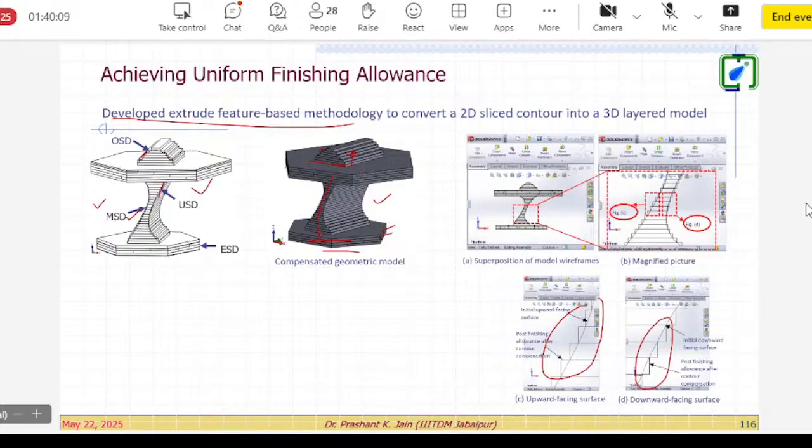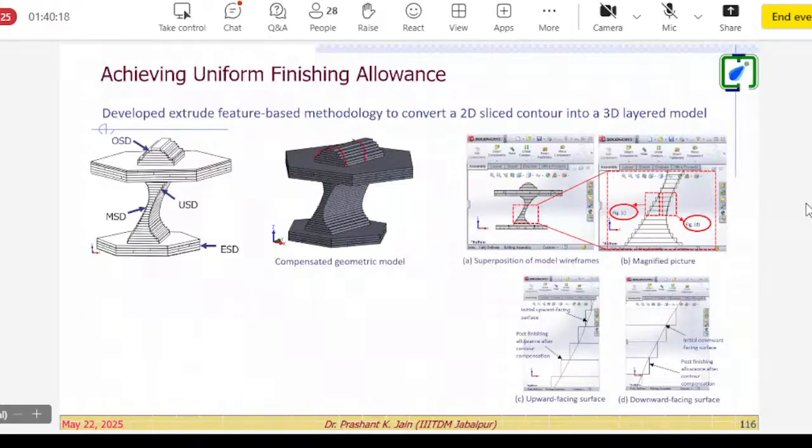After this part, additive manufacturing done, this part will look like this. You will get these stair steps. Means actual part printing will be like this. It is not going to be a smooth surface. Here for visualization purpose, we have taken the layer thickness on the higher side. But the layer thickness is, say for example, 200 micron. So steps of these stairs will be less.